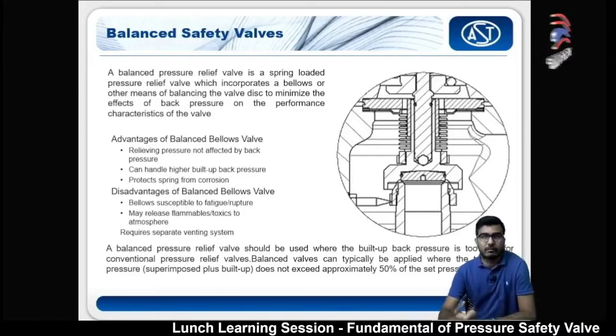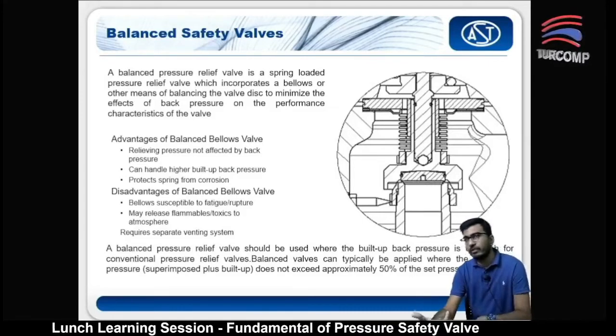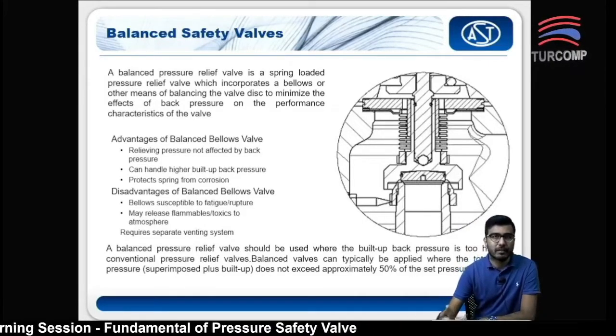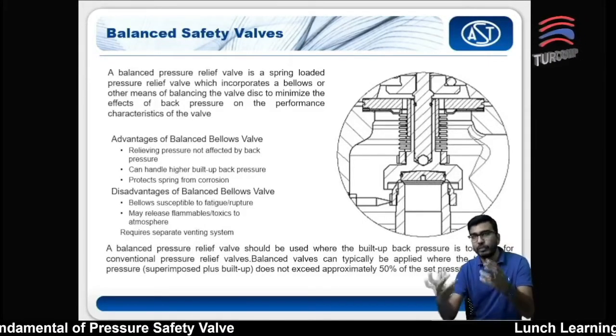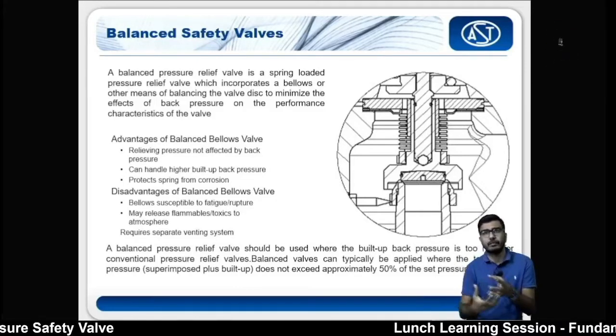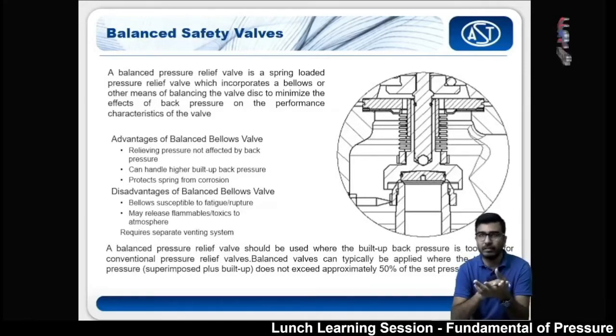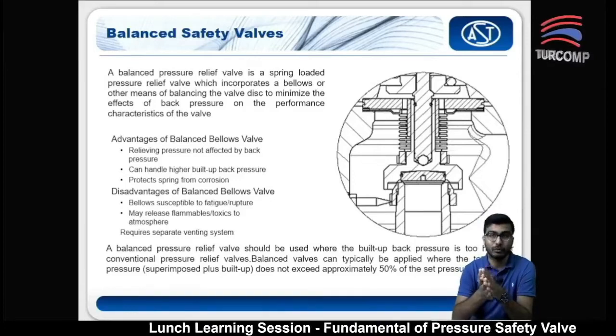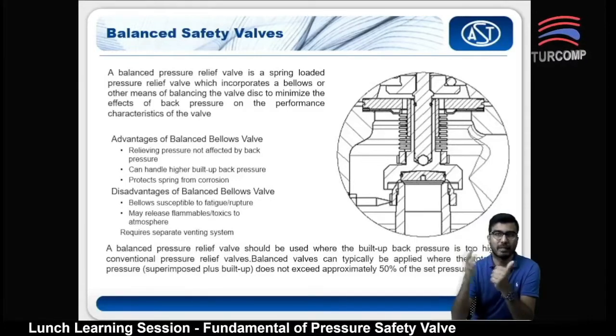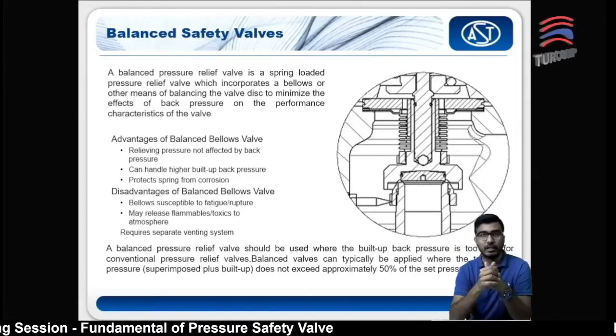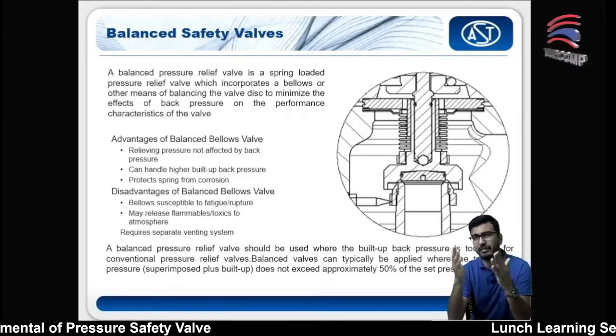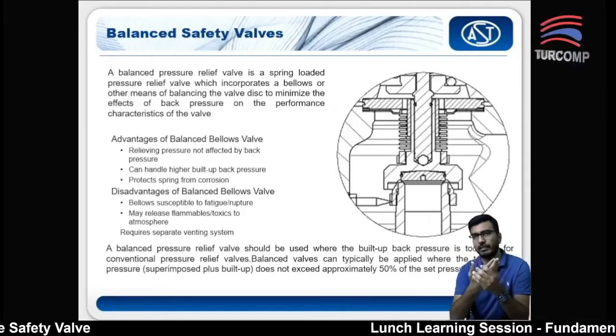So everything has an advantage or disadvantage. The disadvantage is that the bellows itself, being a protection layer against back pressure and the corrosive medium, will get hurt also. So over time it is susceptible to fatigue or rupture. Usually it's metal material, so it is susceptible.